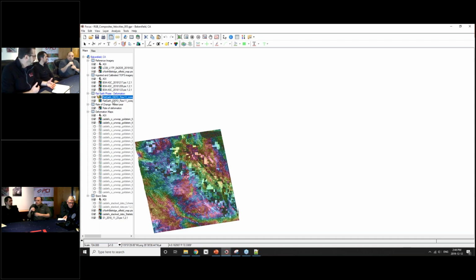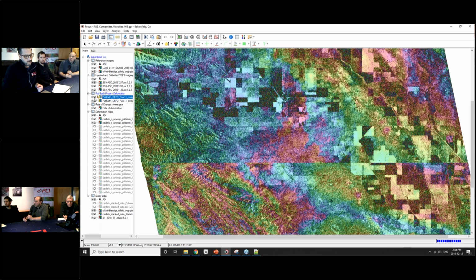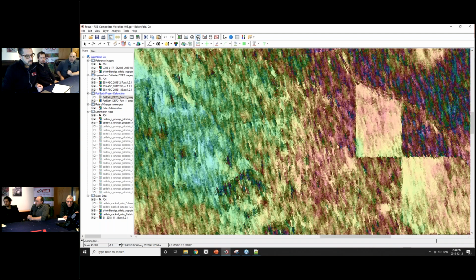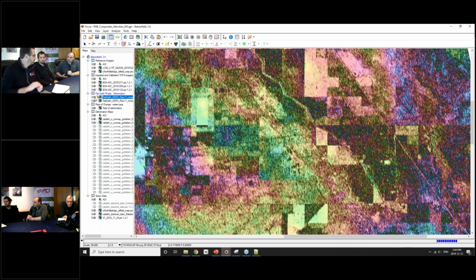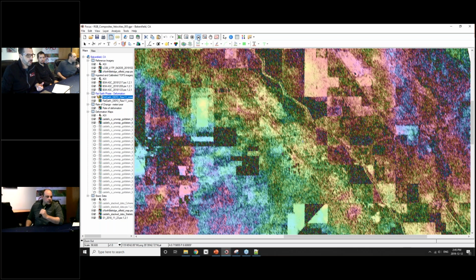One thing that is important when you're doing InSAR processing is that, although we talk about all of those Python scripts, we do inspect the result in a couple of steps. After the raw interferogram generation, we look at both the coherences and the fringe pattern, because if you don't see any special patterns or anything good, it's useless to go further into the processing chain. So when you look at these interferograms, what are you seeing that tells you we're going to have a good result?